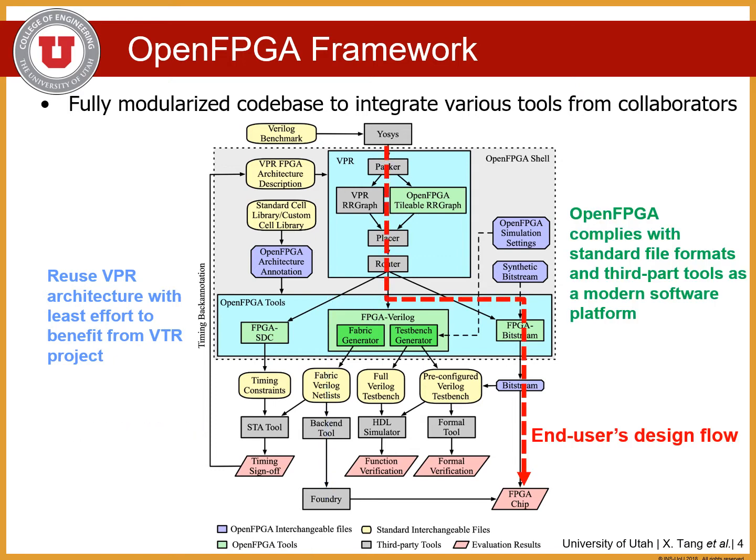The second design flow is the so-called end users flow. This is after you have your FPGA chip returned. OpenFPGA has an internal bitstream generator auto-tuned for your architecture. You don't need to develop your own tools again.